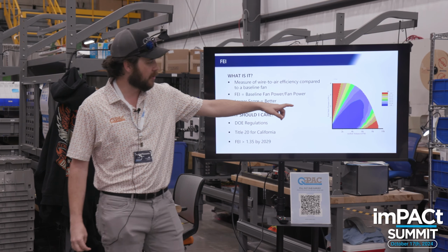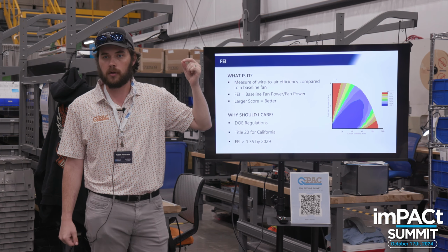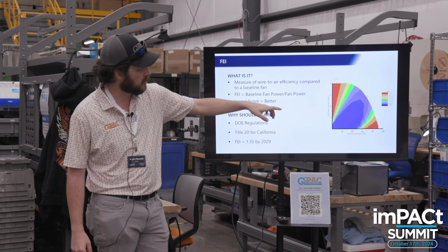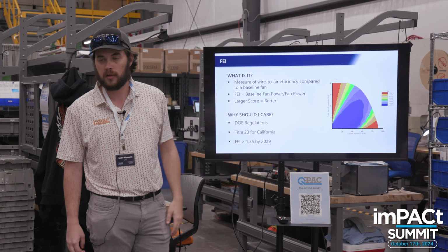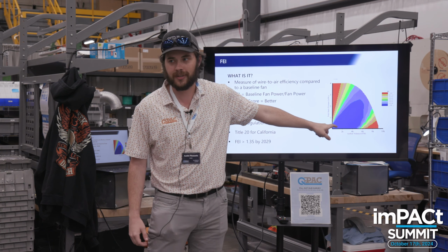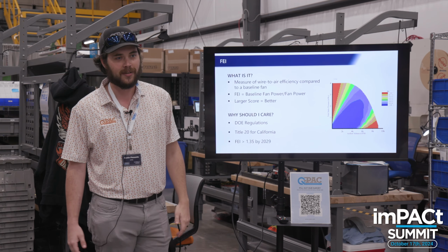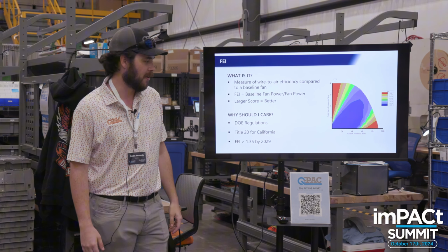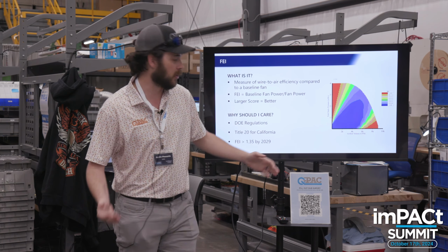One thing I want to point out here is, if you recall the maximum efficiency point that I was talking about earlier, it's not the same as the maximum FEI point, right? The maximum FEI point is actually going to be way down here. But you're never going to design a system down there, right? That's way more fans than what you need, way more horsepower than what you need. It's going to be super expensive and take up a lot of space. You're never going to design down here.